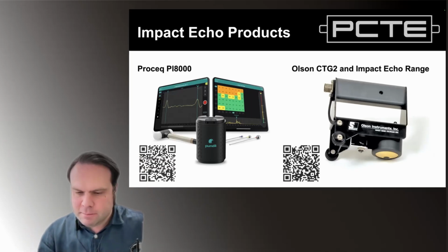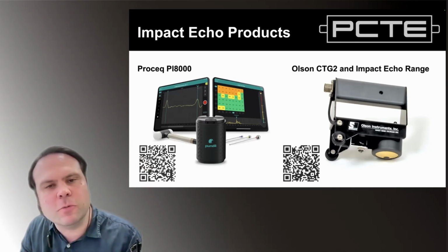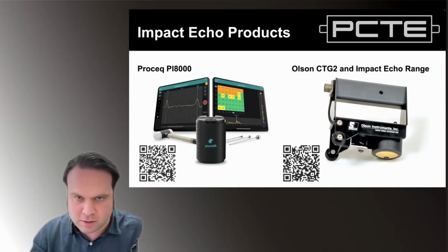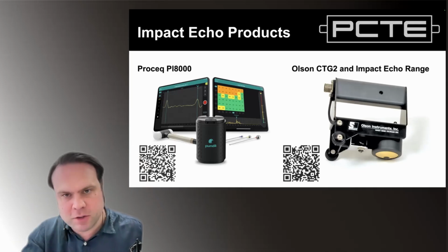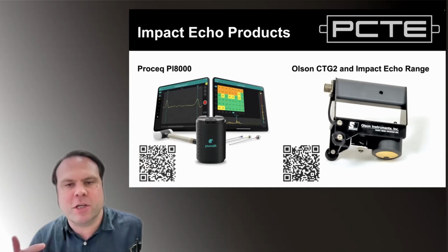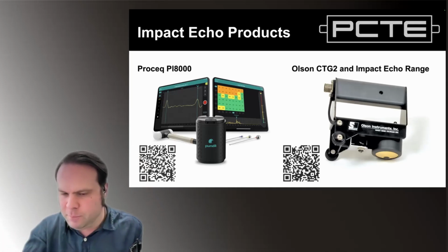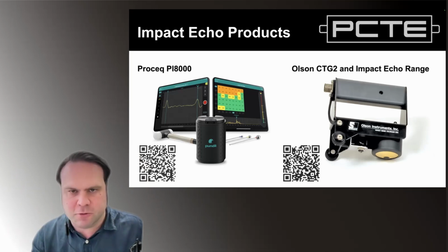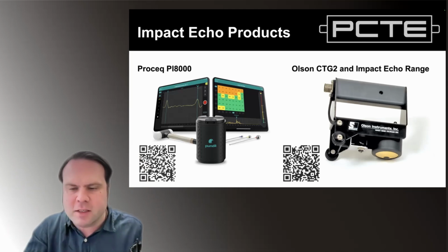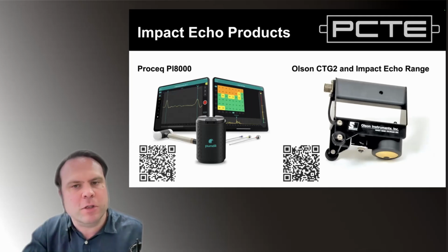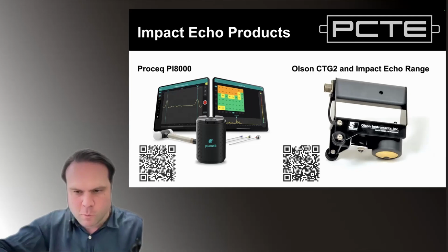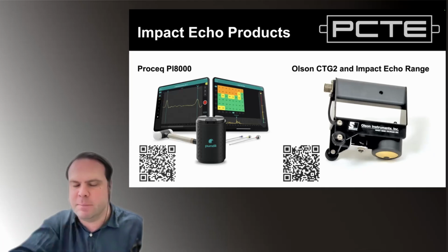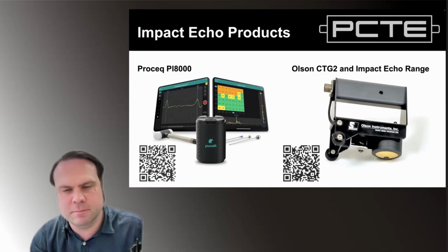Low wave velocity is probably part of what causes a change in frequency when things deviate, but we refer to our results in terms of frequency. So we use an assumed velocity, which means we find results in change in the measured frequency. So your results are going to be in terms of frequency, not velocity. We only consider velocity when we're converting to thickness, and you wouldn't convert your measurement to thickness in this case. So the effect of lowering the velocity would probably be a reduction in frequency, but we measure frequency. We don't consider velocity in this case.